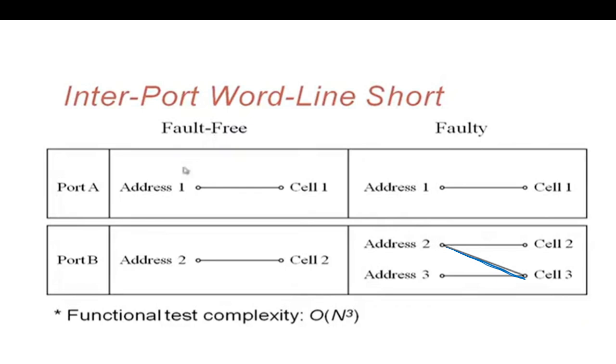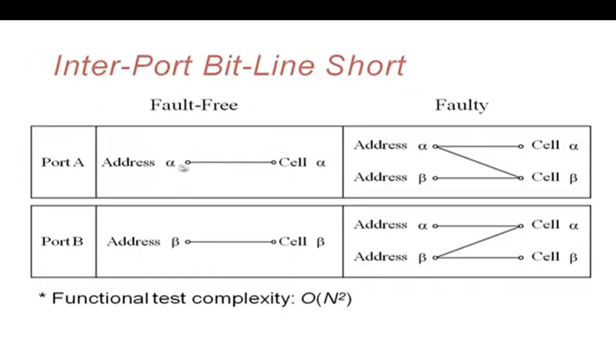Next, for the interport bit line short, this bit there is a short, and this bit you can see there is a short. So the functional test complexity is big O of n square.